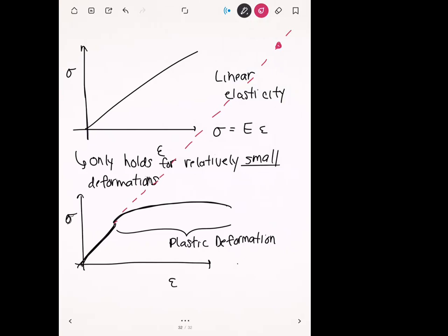And so if you ever start to see large deformations in your model, either you may have made a mistake in setting it up, or if you didn't do that, then you have to make sure you turn on plastic deformation so that you get the right behavior. Any downside to just keeping that plastic deformation option on all the time?